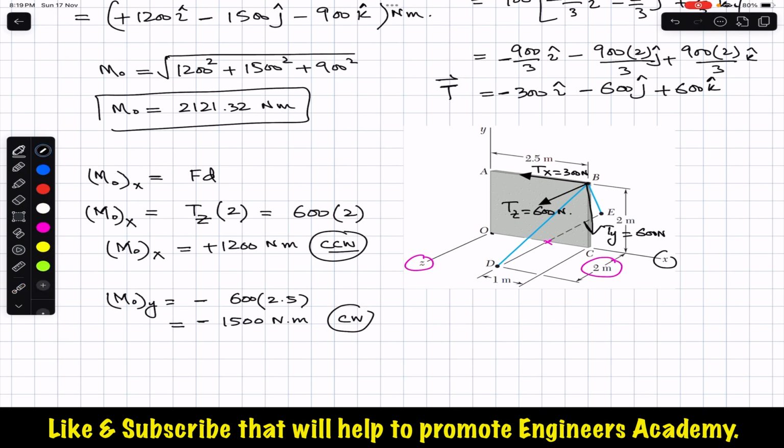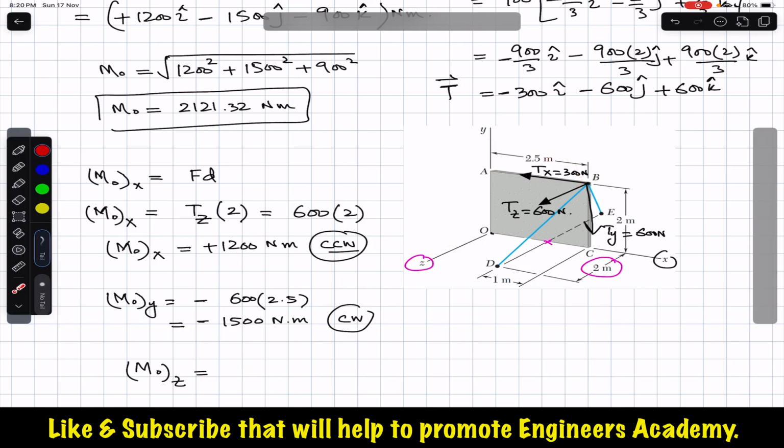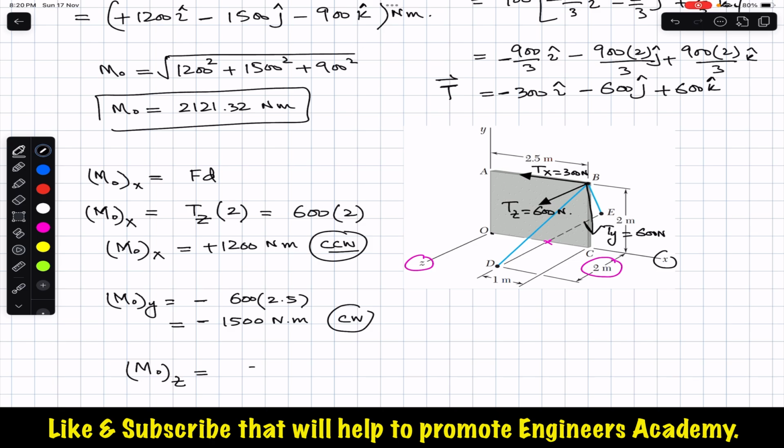Similarly, we can say that the moment at O about the z-axis is equal to, so again we have to look for these three components again. So the x component is going to rotate this portion of the wall in this direction, like this, right? It can rotate like this, or it can rotate like this. So we can say that Tx, which has a magnitude of 300, is going to produce the moment about the z-axis in this direction. And if we curl our right hand fingers in this direction, the thumb will point out in the positive z direction.